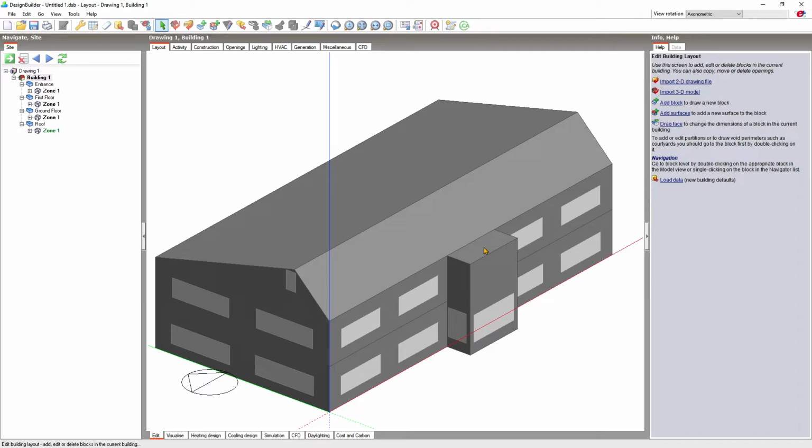An outline block is created and edited in the same way as a building block, but it's simply a 3D shape used to aid geometry construction and does not add elements such as walls, floors, roof, etc. to your model. Outline blocks are very useful in the creation of more complicated models because they can be manipulated freely without causing block intersection errors. Once the required geometry has been established, outline blocks can be converted to normal building blocks with attributes that are included in your model and simulations.